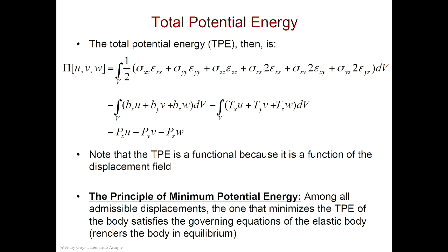You saw that already. You applied that concept for the spring problem. We applied load to the spring. You calculate total potential energy, remember? 1/2 kd squared minus the load applied to the very end, right? And we minimized that function relative to the displacement. And what did that give us? That gave us the equilibrium of the spring. If you recall, we went through that exercise. So with that said, I could apply this concept to determine what are the governing equations? What are the equations that describe the deformations of the problems I have interest in?